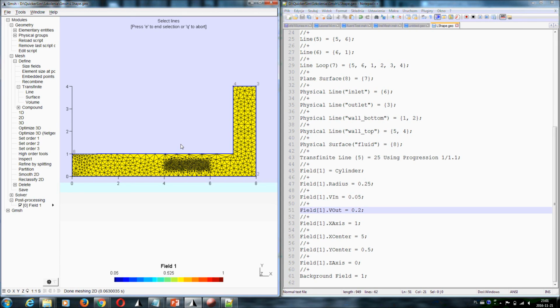You can very easily define the mesh resolution with this pretty advanced technique, and I encourage you to try it, because mainly for computational fluid dynamics simulations, it is extremely important to refine your mesh in places where many flow features exist and where you have very complex physics.